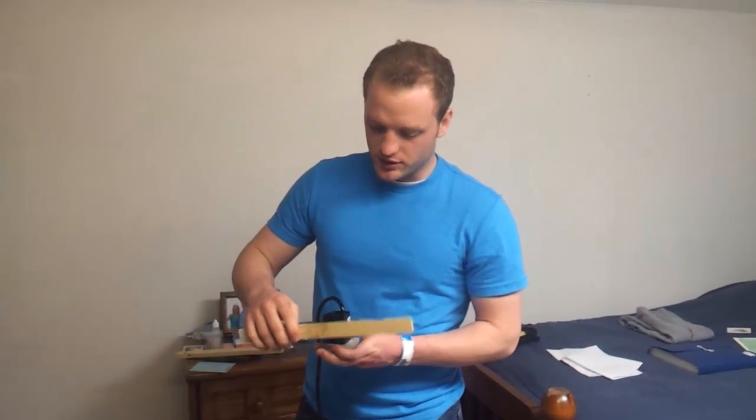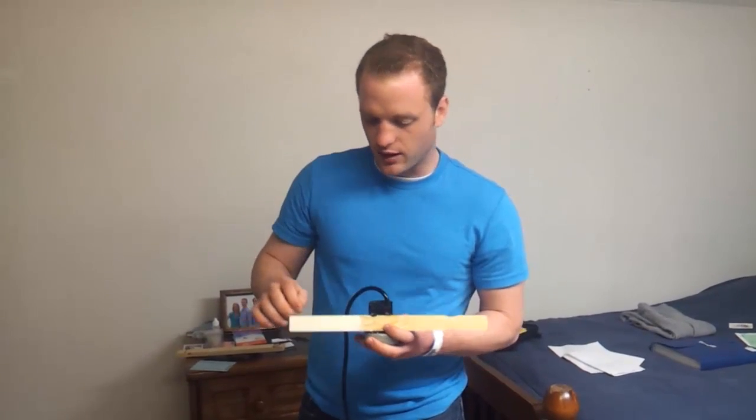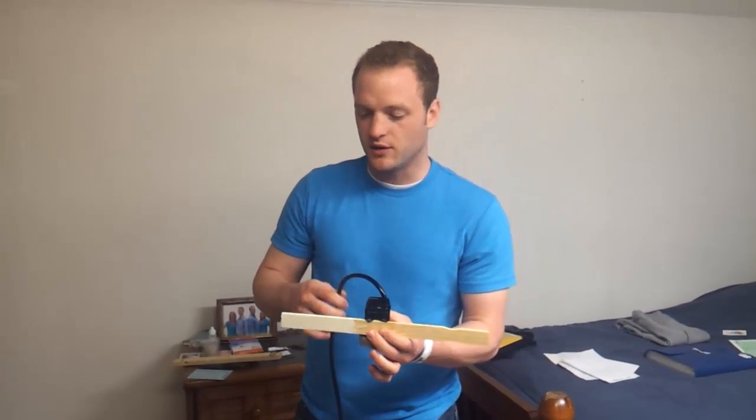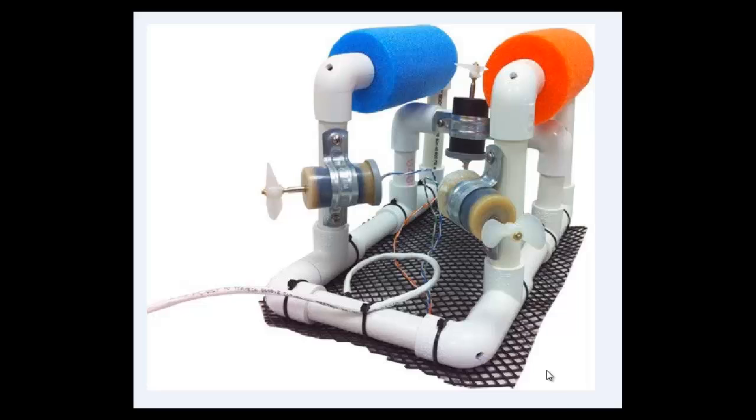So for the last part, you need to figure out how to attach it to the SeaPerch. It's really simple. You can use a rod. You can use any sort of rod. I'm going to use this wooden paint stirrer. And you're going to super glue it to the bottom of your pump like so. Right? So that when it's oriented like this, with the pump facing down, you can zip tie it here and here to the SeaPerch here and here.